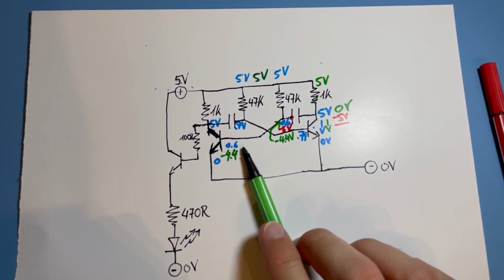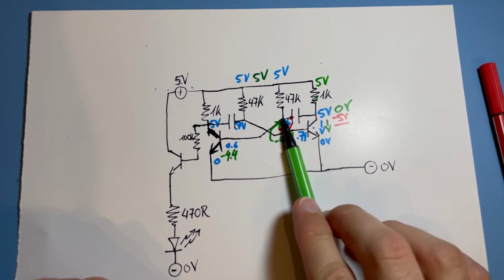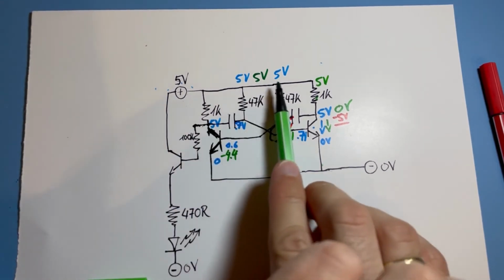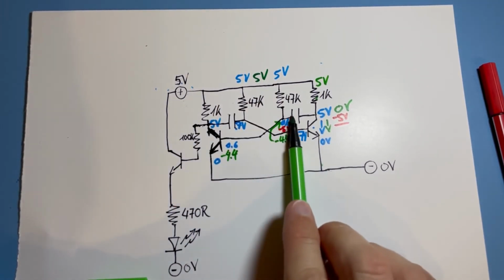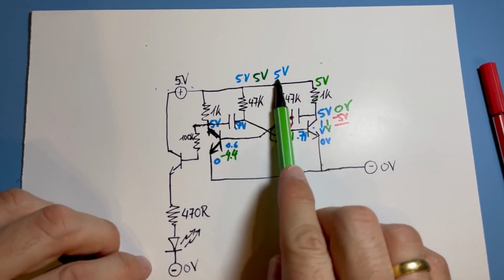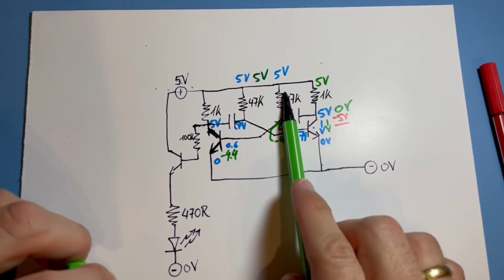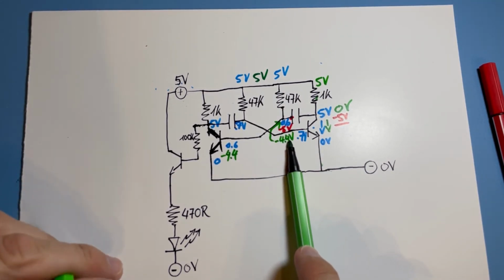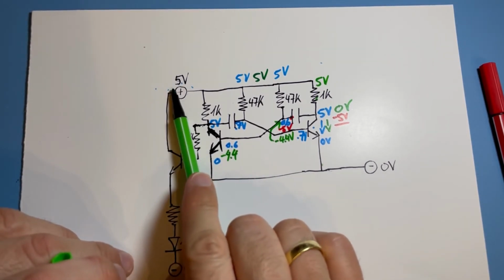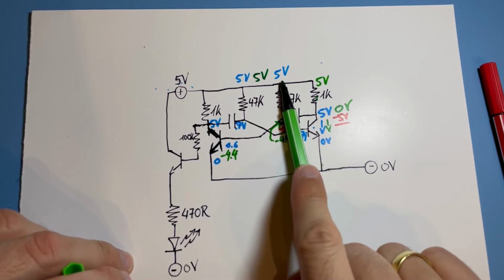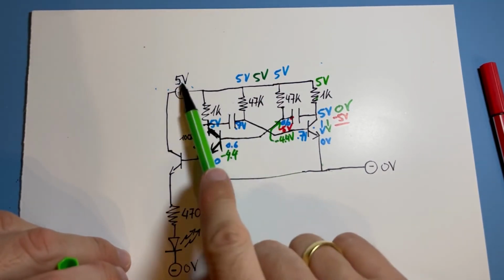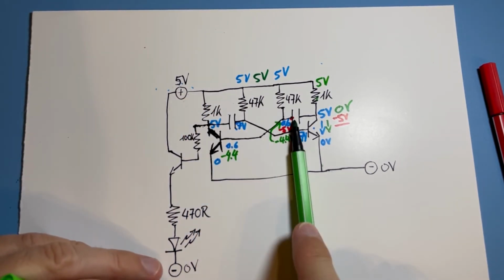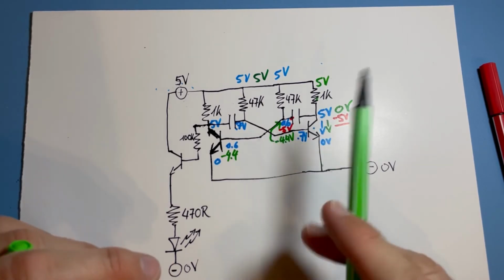And what has to happen now is that this minus 4.4, what happens with it? That's a stable situation at first. But because we have a resistor here that connects to plus 5 volt, the plus 5 volt pushes current through this resistor to this negative, because minus 4.4 volt is a negative potential, plus 5 volt is a positive potential, so we have a potential difference, and there is current, positive current, like technicians want to see it, and it's quite correct every time. There is current flowing here to this transistor. And it's flowing, and it takes some time.